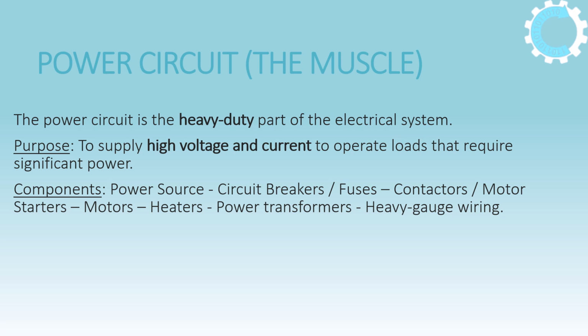Contactors or motor starters, which are electrically operated switches that connect or disconnect power to large loads like motors, are also part of the power circuit. And by the way, these are the most common load in a power circuit, converting electrical energy into mechanical motion. There might also be some heaters which convert electrical energy into heat for some heating or drying process.